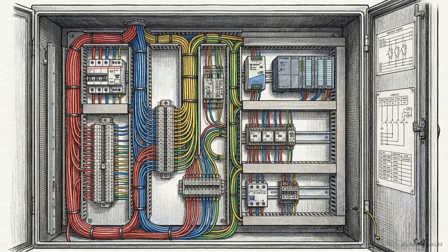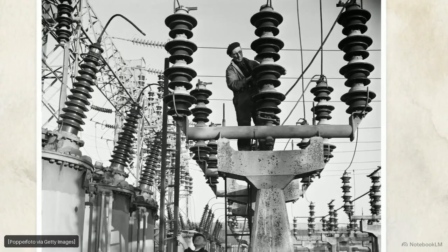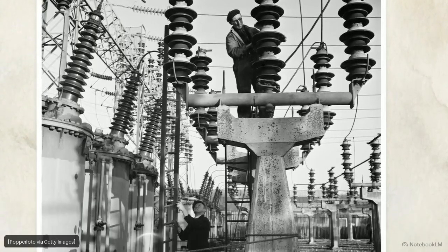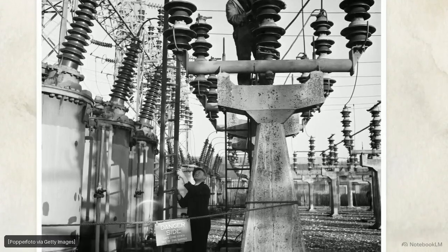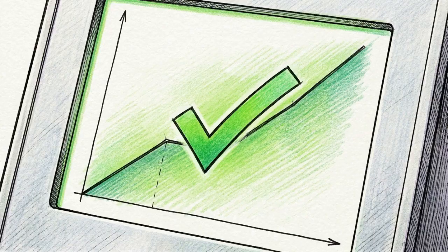Because the system relies on interconnected current transformer polarities, precise matrix math, and slope calculations, a single reversed wire during installation will cause a false trip. Rigorous commissioning is required before a transformer is ever connected to the grid. This process begins with secondary injection. During secondary injection, technicians inject simulated fault currents directly into the digital relay. This proves that the software's dual slope and harmonic blocking logic function exactly as designed.